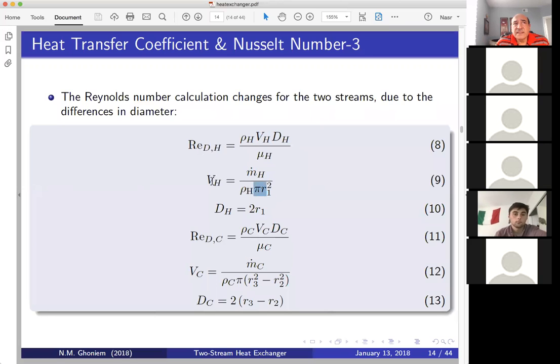So if you look at it, the velocity times pi r1 squared is like a volume swept by the water in 1 second. So in 1 second, as the water goes through, you get a slug that has a volume of pi r squared times v. If you multiply that volume by the density, you get a mass.